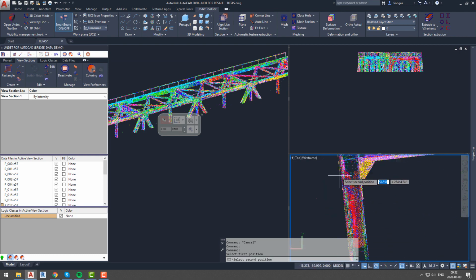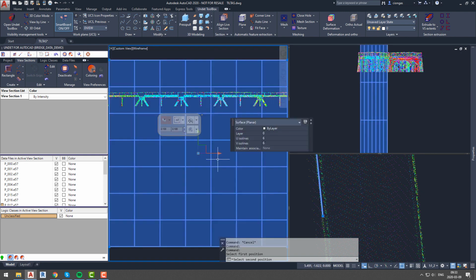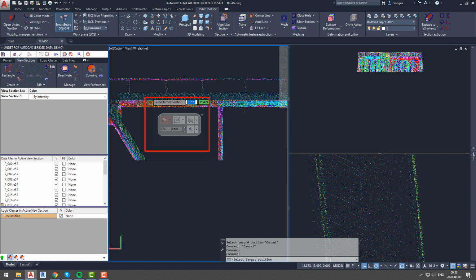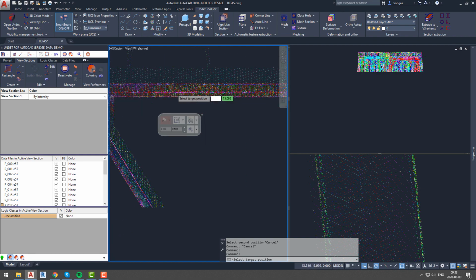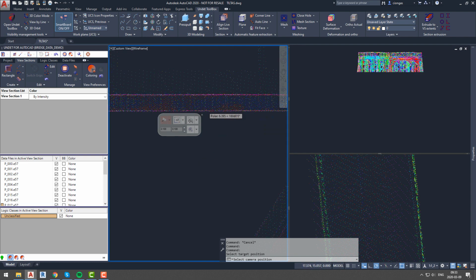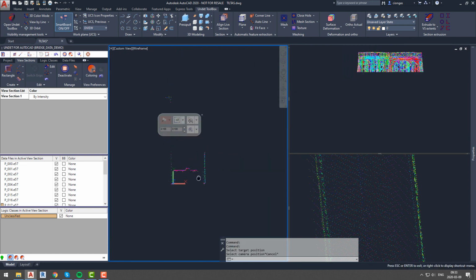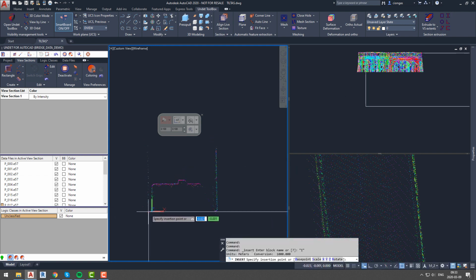end of same element. This will create new section, but since we are interested in element structure and we want to be precise on that we will create another section, this time profile section, and we will mark 2 points of same element. As you can see, this created new section and new UCS. Now we see 10 cm size profile section of our beam, so we are able to draw it.